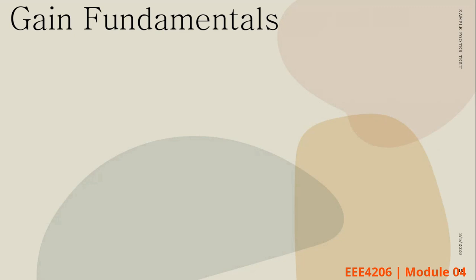Then let's look at the gain, because when you talk about an amplifier, without talking about gain, there's nothing. Because without a gain, you have not amplified anything. Maybe if the gain is 1, sometimes you find the gain is 1. Especially if there is a bridging network that you want to build, you want to transfer exactly what you receive to exactly the output, but you need a bridge in between. You can design an amplifier that has a gain of 1. Okay, but in most cases, gain is more than 1.